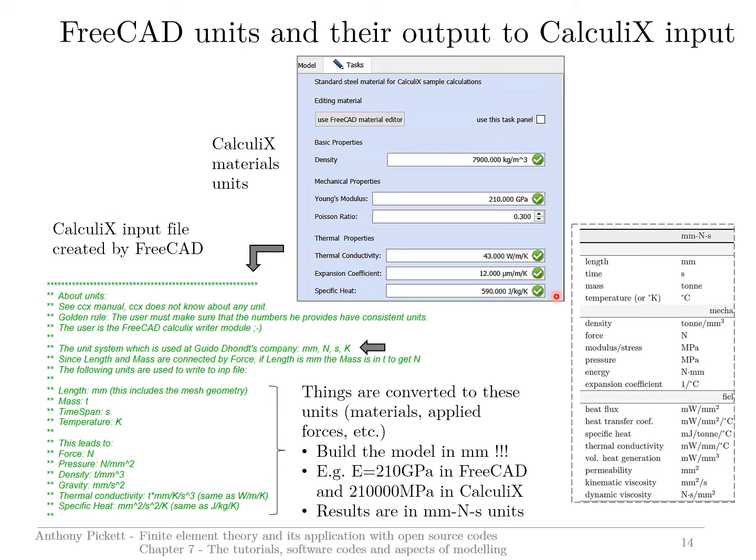So if you want to change anything, it's possible. You would actually have to activate this tab here so that you can edit numbers. If you want to modify this to be aluminium, you could click here and change a number, and you could change that to 2,800 kilograms per meter cubed. So you can modify things, but stick to these units when modifying anything within the materials database or anywhere else in the code.